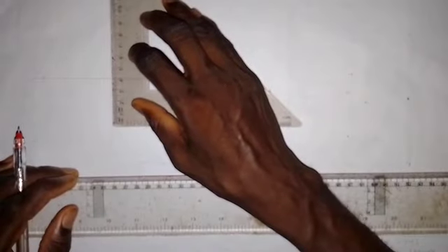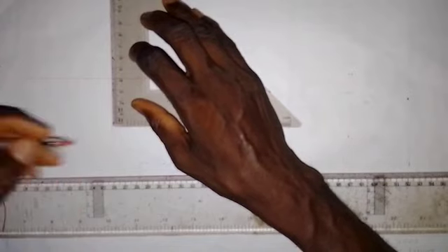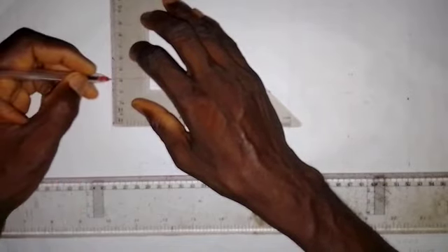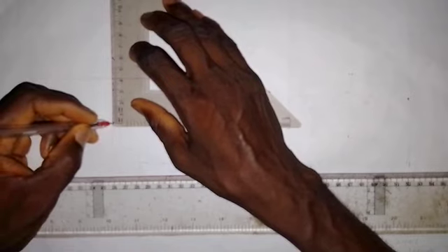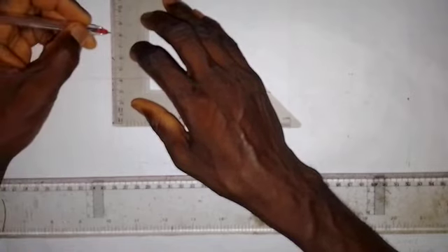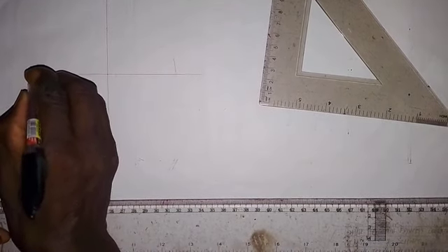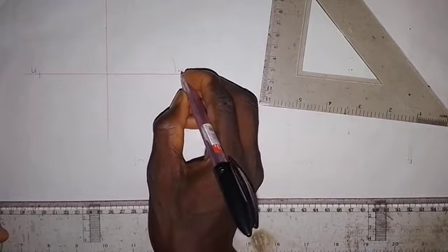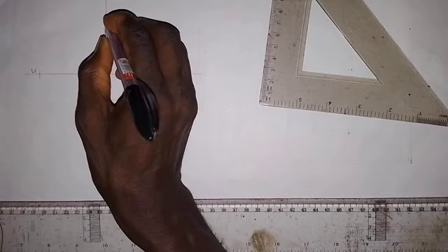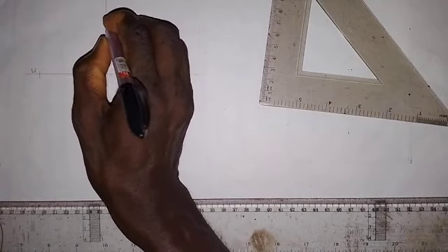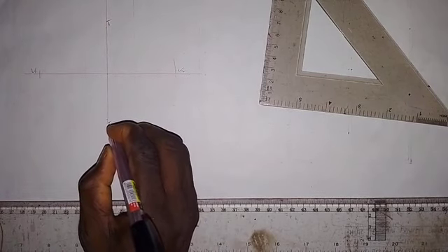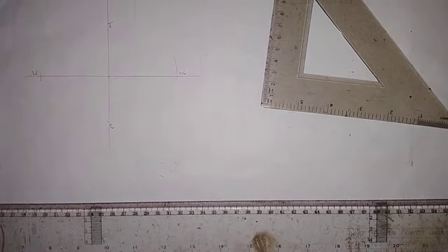So I want to take a measurement of the minor axis on the vertical line. From this point here, we take 40 millimeters down, and we take 40 millimeters up. That is 80 millimeters. So I'm going to label this point. I will call this point V1, and I will call this V2. This point here I will call point T1, and this is point T2. So this is how I want to label it. There's nothing wrong with the labeling.